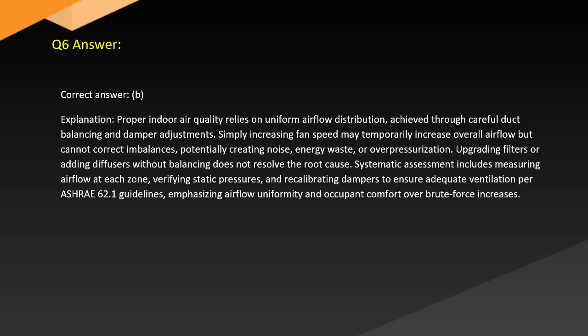Systematic assessment includes airflow at each zone, verifying static pressures, and recalibrating dampers to ensure adequate ventilation per ASHRAE 62.1 guidelines, emphasizing airflow uniformity and occupant comfort over brute force increases.